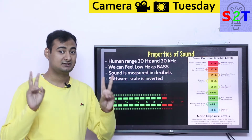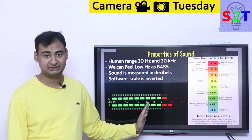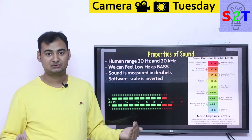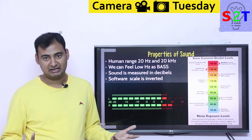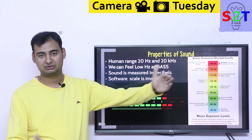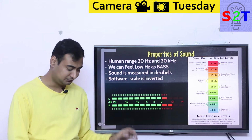This is what people classify as a hot signal. It means it's reaching 0, and you always want to be below that. For a YouTube video, people will say -6 to -12. For TV, because TV has much higher standards, it's -20 to -24. There is a whole list that you have to go through to understand this. So this is the property of sound.